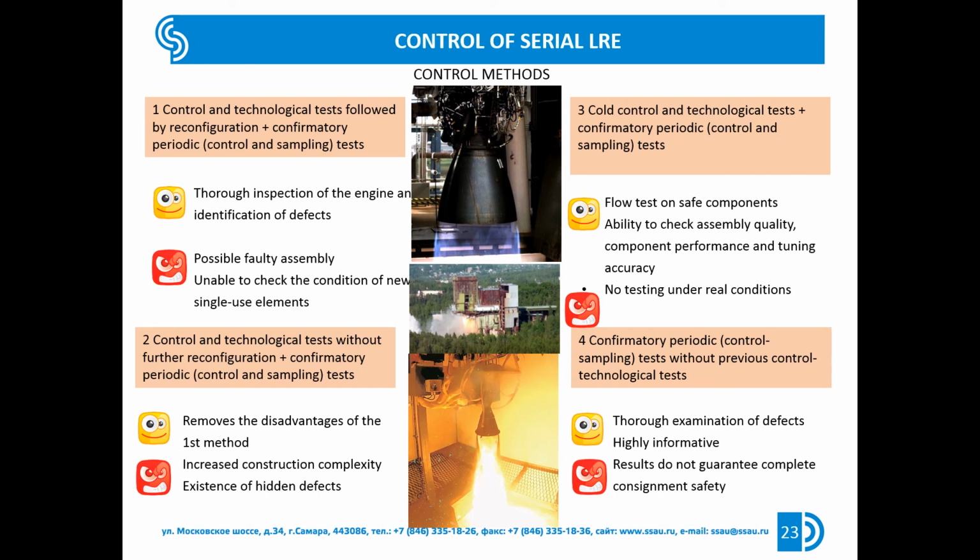In some cases, process control tests are not performed and product quality control is carried out only by confirmatory periodic tests. Such a method may be considered appropriate when the effects of fuel components on the structural components of a test and the subsequent prolonged storage of LPRE lead to a reduction in its reliability. However, with this method, the period set for confirmatory periodic testing or the batch size from which the LPRE is selected for sample testing will usually be shorter than when pre-process testing is provided for.